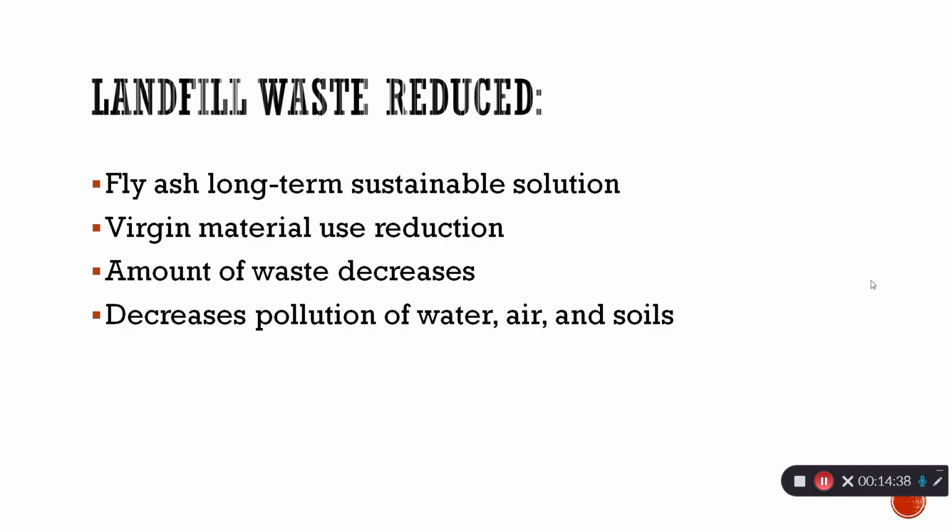When replacing cement with fly ash, the demand for virgin materials reduces and the amount of waste sent to landfill significantly decreases. An environmentally responsible society must develop low-carbon infrastructure through optimum use of cement and proper use of fly ash, a waste byproduct that can significantly pollute nearby water resources, the air, and soils otherwise. Rather than being disposed of, fly ash can be useful both environmentally and economically if it is used in concrete. So, by this replacement, environmental concerns about disposal are addressed for fly ash.